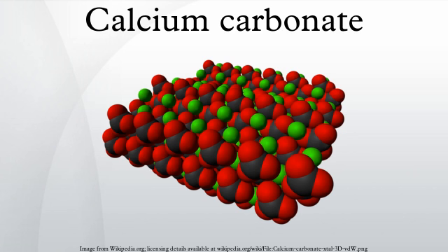Calcination equilibrium. Calcination of limestone using charcoal fires to produce quicklime has been practiced since antiquity by cultures all over the world. The temperature at which limestone yields calcium oxide is usually given as 825 degrees Celsius, but stating an absolute threshold is misleading. Calcium carbonate exists in equilibrium with calcium oxide and carbon dioxide at any temperature. At each temperature there is a partial pressure of carbon dioxide that is in equilibrium with calcium carbonate.